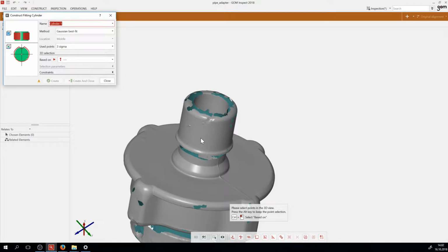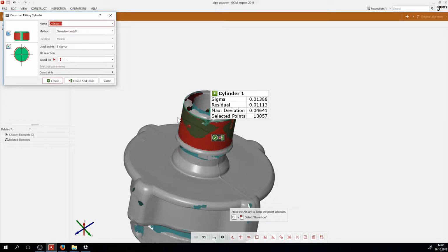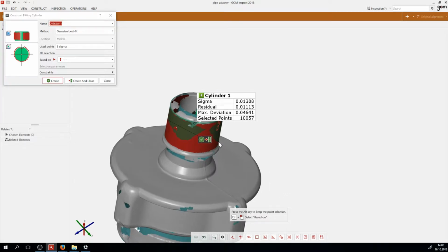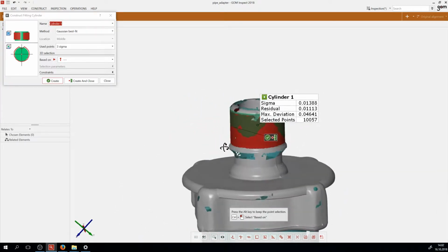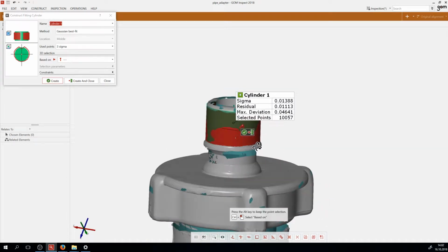When you have cylinder selected, you can just point at one cylinder based area in the mesh, and the software is going to select it on its own. And how do we do that? Just hold Control and press the right mouse button, and you see now here it selected the whole cylinder. That is what we needed.